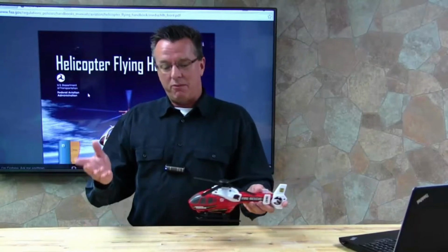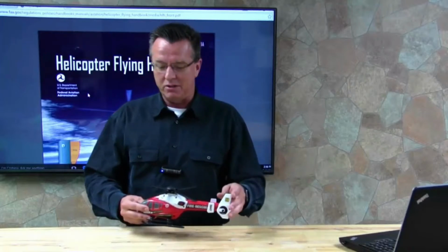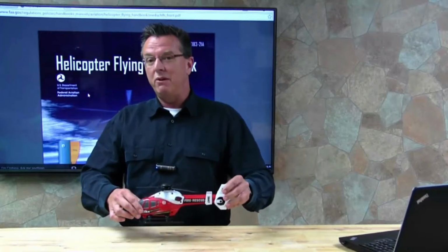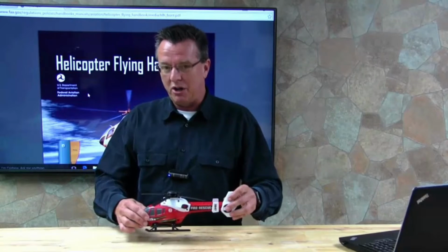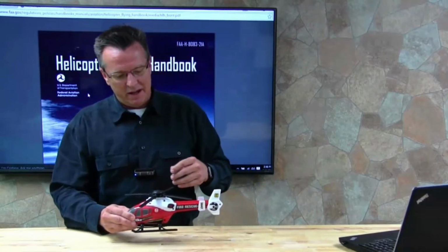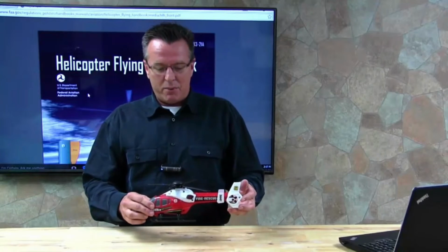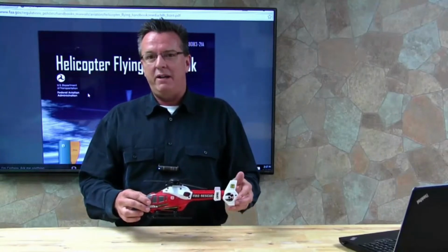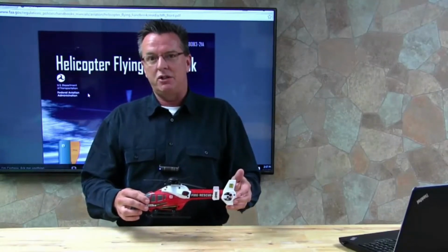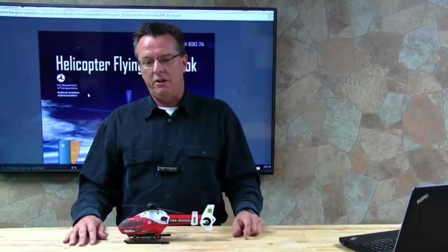And when that happens to you for real, I've only had it happen once where an engine failed during a hover, but it was after maintenance. We were hovering for a few minutes to make sure everything was good before we took off, because we would take off over a lake, and the engine just quit. And I can tell you after practice, as a CFI, you're doing them all the time, you don't even think about it. The engine stops, you go right pedal and set it on the ground.